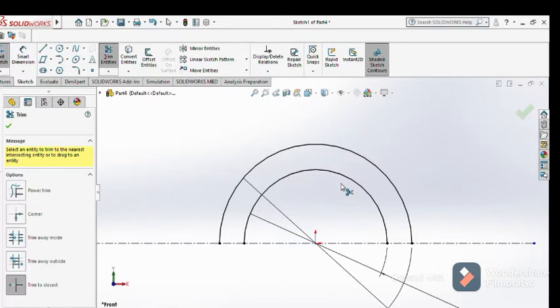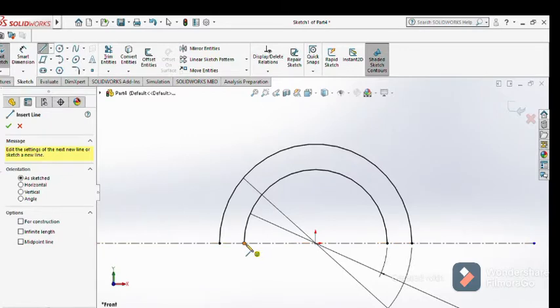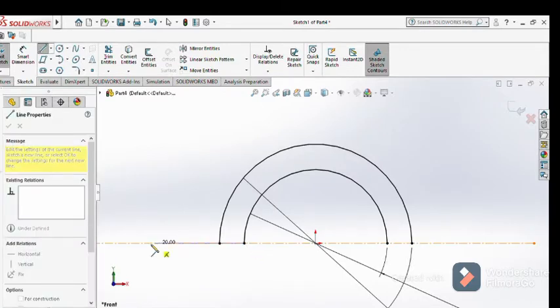And then from there, since we have the 2 circles, from here what we do is we start putting in, don't forget guys, this must be fully defined at all times. So from here it's then that you can put in our lines. I'm going to start by drawing my line here, first start drawing my line there. Since it has a certain measurement, we'll figure it out very soon.